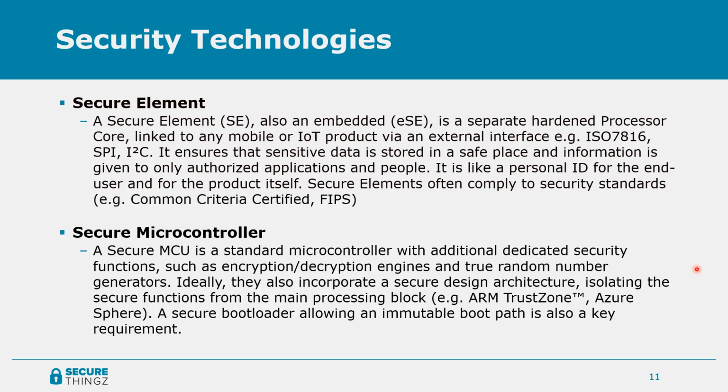It's basically like a personal ID for the end user and the product itself. Now, often secure elements comply to certain standards such as the Common Criteria, which we'll cover a bit later. Now, a secure microcontroller is basically a standard microcontroller with additional dedicated security functions. These can accelerate encryption, decryption by having engines on board, and all of them should have a true random number generator incorporated on the device.